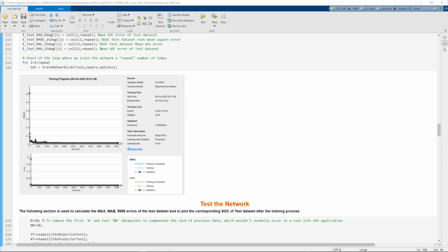As described in past webinars, Simulink provides a natural path for BMS algorithm development and automated code generation. Starting from MATLAB release 2020b, Simulink offers a block called Predict with the functionality of a trained deep neural network. This will allow us to include an SOC estimation feature into a BMS model.